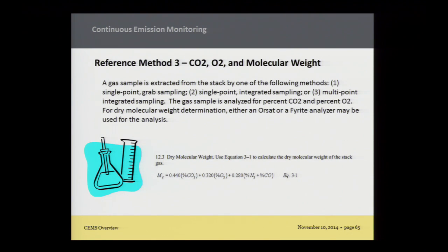So reference method 3, CO2, O2, and molecular weight. So a gas sample is extracted from the stack by one of the following methods: a single point grab sampling, single point integrated sampling, or a multi-point integrated sampling. So there's a bunch of methods within method 3.